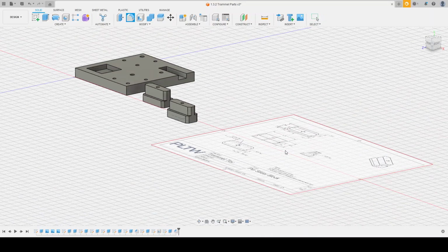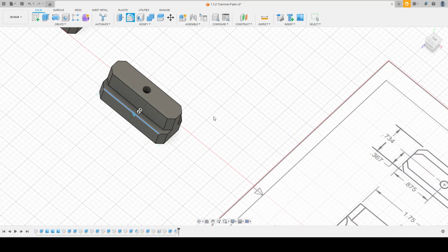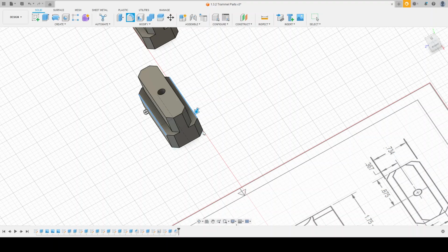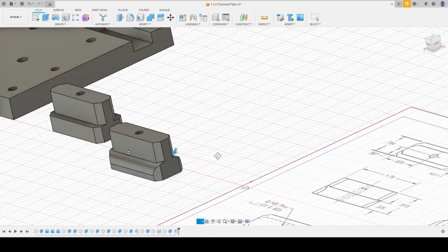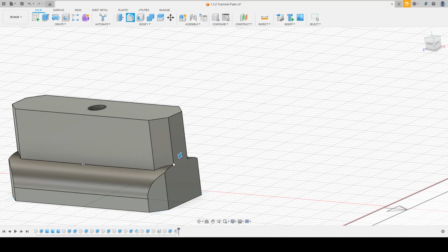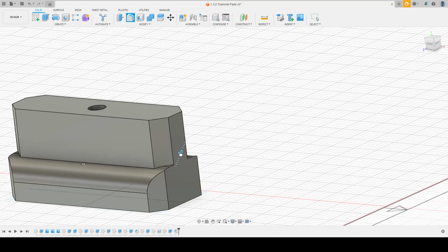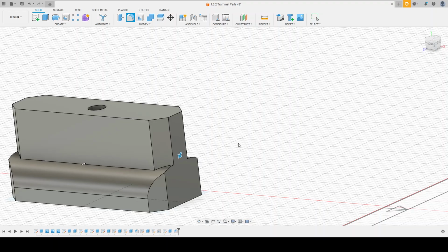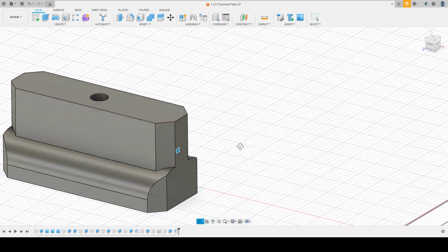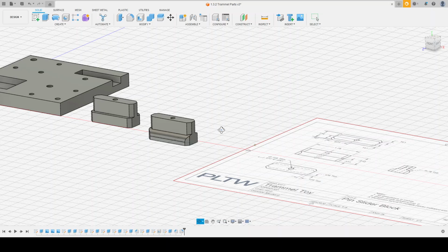So we're going to add a fillet, and it says a radius of 0.25. And let's see, if we add it onto those sections at 0.25, we get this more interesting geometry coming up. And see it kind of shapes over. If I back this off, it will shape all the way down that line until it kind of meets with the start of the object. So now we have our round over for our pin slider. We hit enter. Now that object is complete as well.